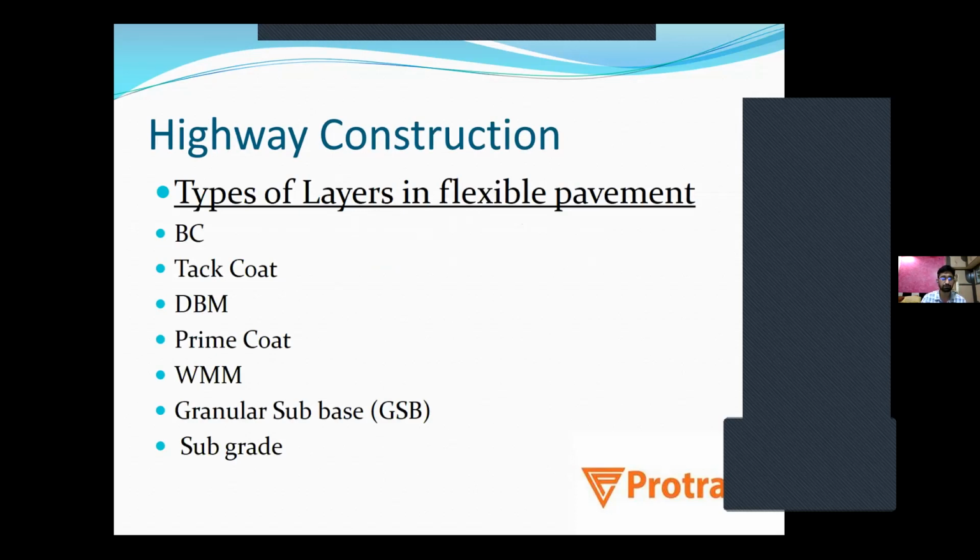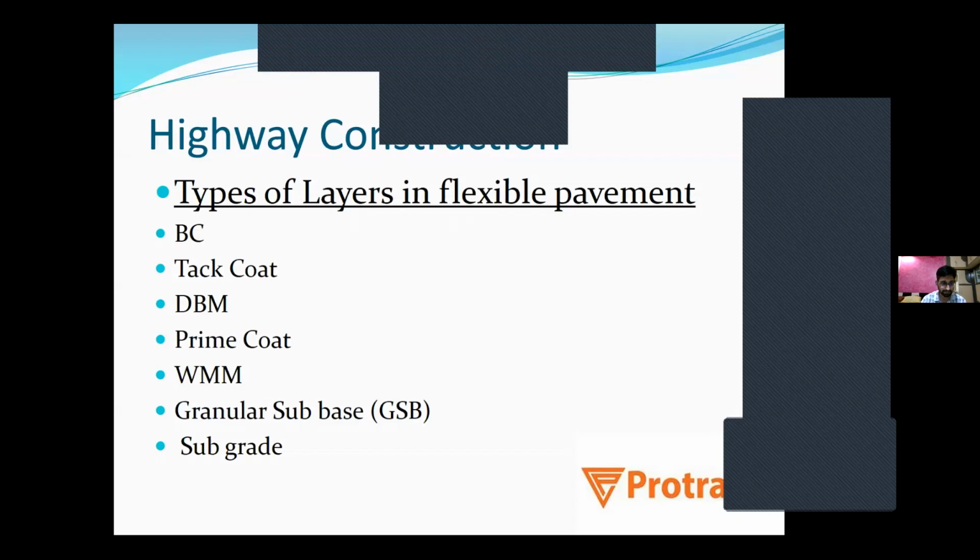First of all, we will go with subgrade. The layer of subgrade is prepared. Then after particular compaction and after obtaining particular width of subgrade, granular subbase is executed. After that, wet mix macadam is done.